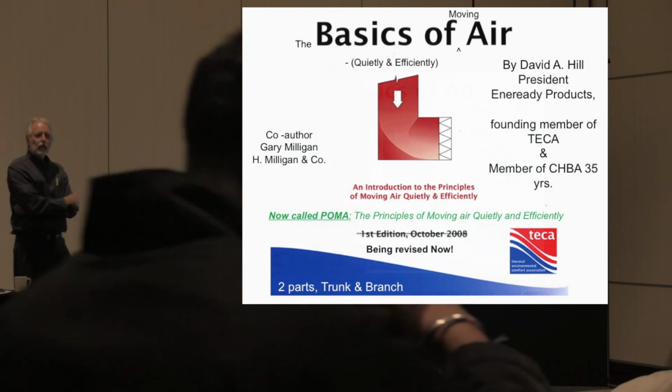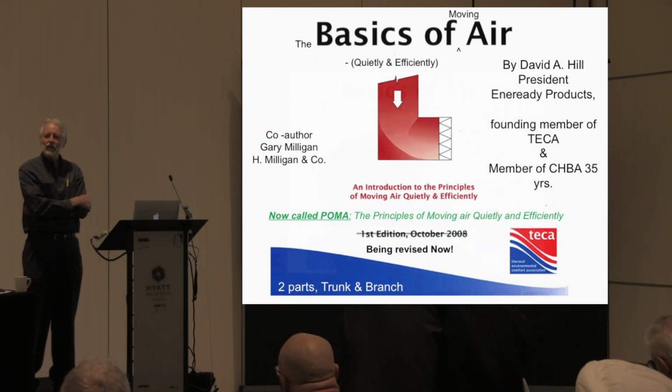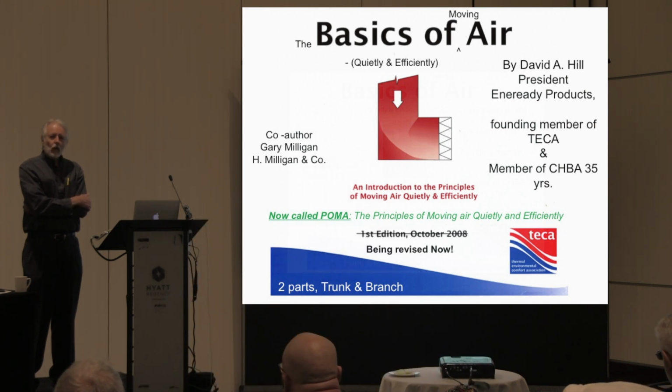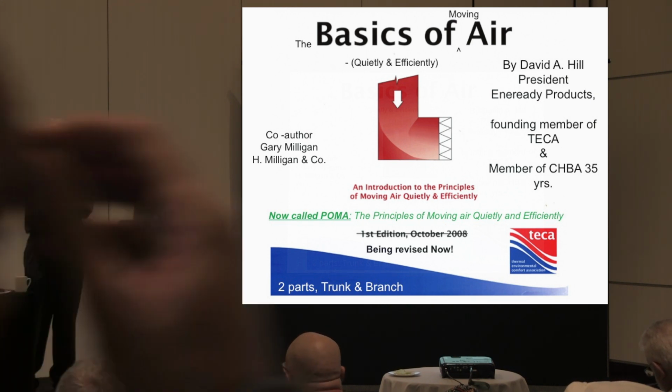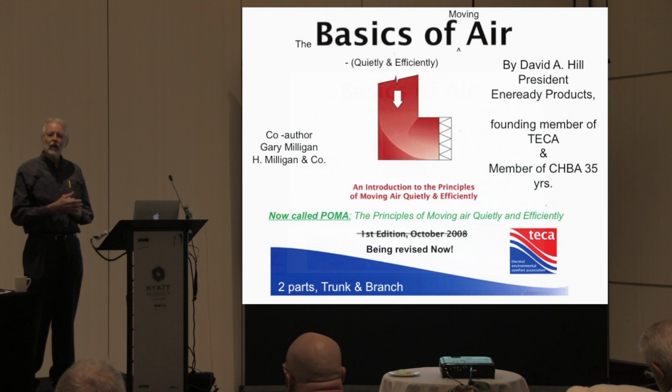In the 1930s, we had gravity furnaces that worked by convection currents. They worked beautifully because the duct was big, it was smooth, it was short, it was fat. When we entered the 40s and 50s and we started to introduce fans into heating and cooling systems, the fans didn't have to be very powerful because we had a legacy of building good ductwork systems. So it was big, short, fat, and free-flowing because we came from a time when we had no fans at all and gravity had to do the job.